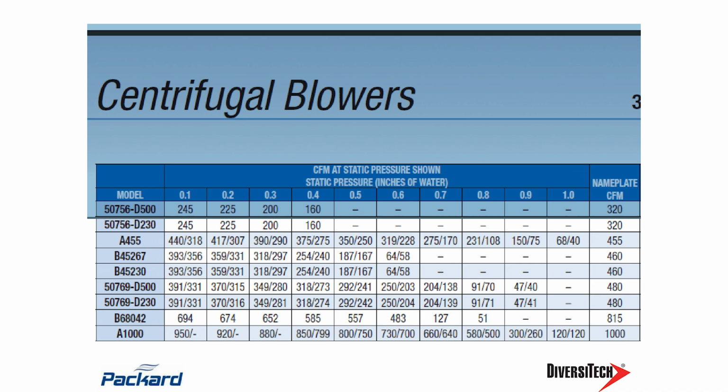So if you need 1,000 CFM at 0.4 inches, you need to let the wholesaler know that that's what you need in order to get the right one. So we have to look at the performance we need at specific static pressures. Typically on a furnace, we might see about 0.8 inches of static, but that will have static pressures from 0.4 up to about 0.8 generally with our static.